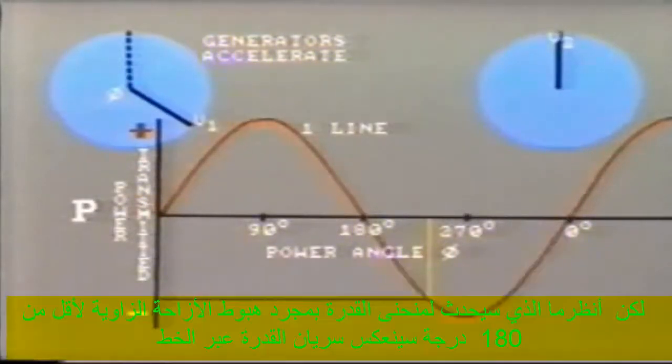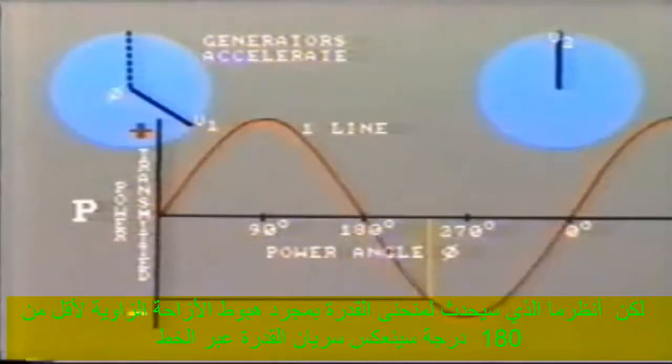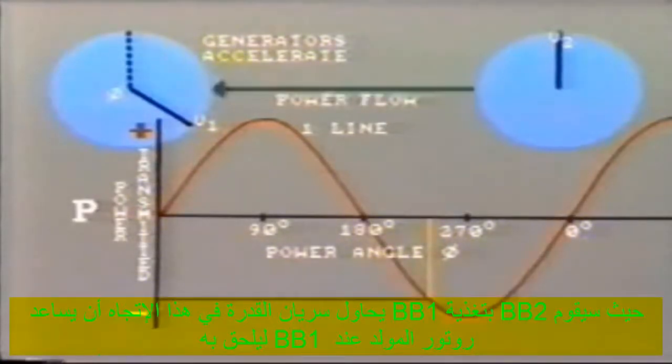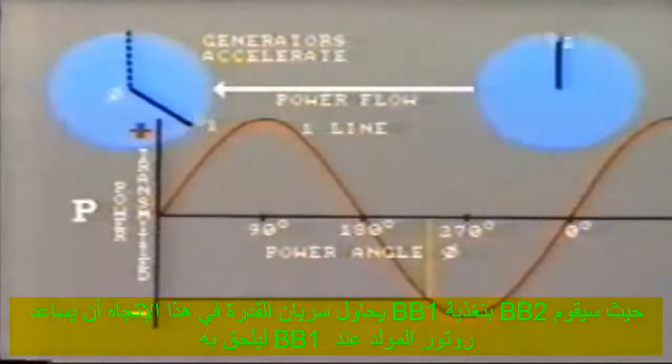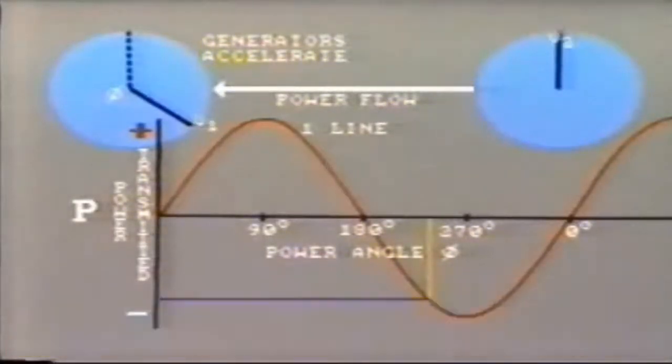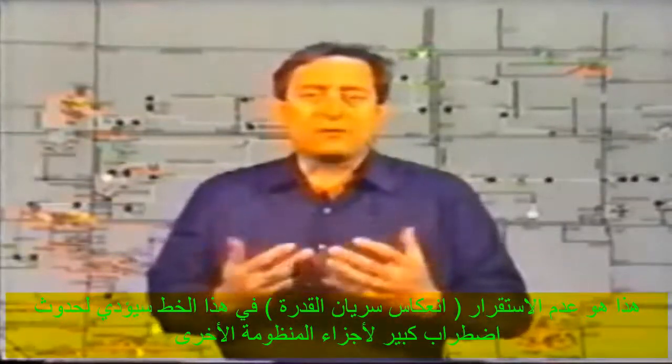But look what's happening to the power curve. Once the voltage displacement falls beyond 180 degrees, the power flow along the line reverses. Bus 2 is now feeding bus 1. The power flow in this direction is trying to assist the generator rotor at bus 1 to catch up. This is instability.